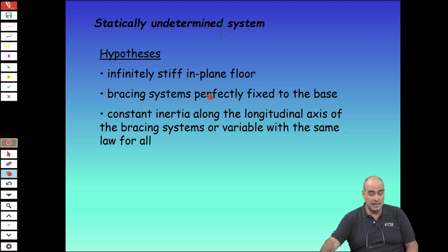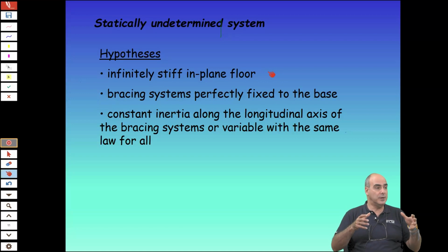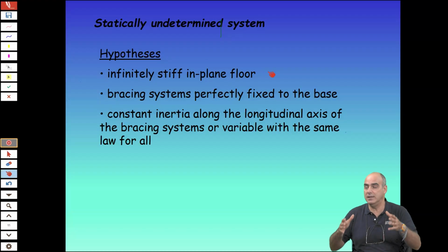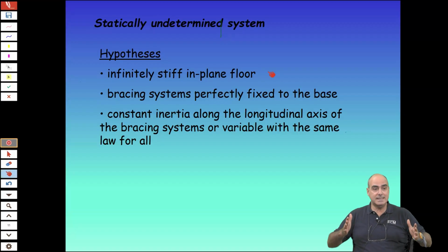The other thing that it's not detailed here, but the floor must be infinitely stiff in its own plane, but also must be effectively connected to all the elements which have to resist the lateral loads. Because otherwise, since we have said the inertia force is applied to the floor, there is no way to transmit it. So this is important. Then the bracing system is perfectly fixed to the base. So this is another thing that we have to guarantee.